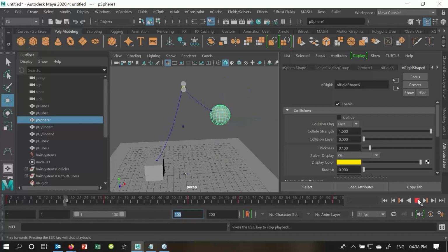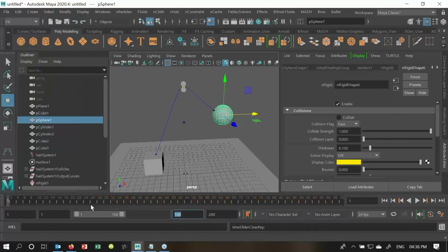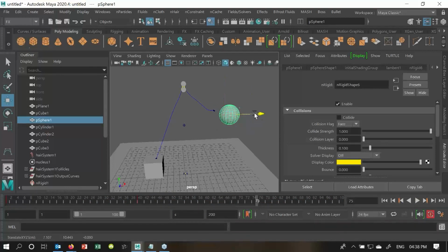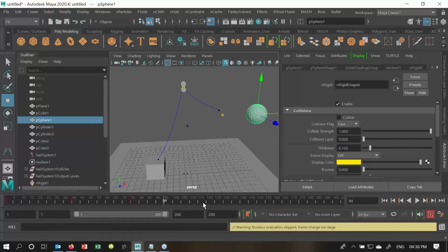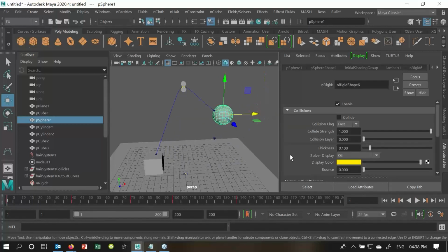Now why did that happen? Because if you see, this has become a very fast animation. So I'll try to reduce it to a little bit slower. Say set key on this. I'll select my object, set key, between 240, set key, or 70, just try to slow it a little bit, set key. I'll scale it, between 70 to 200 is the same. Then after that it is slowly coming down, set key. Turn that off, start and play this. Again, this becomes very fast.